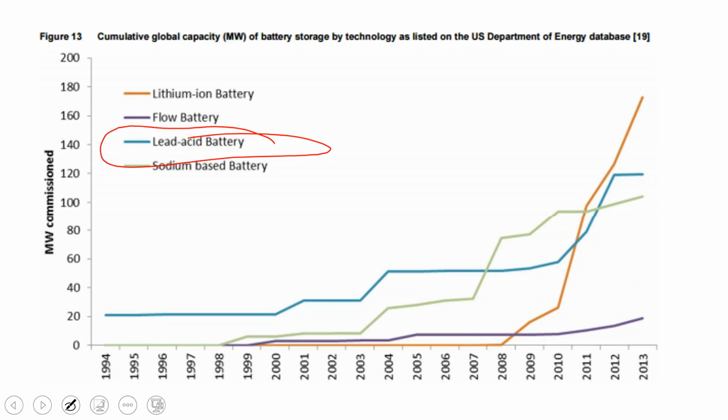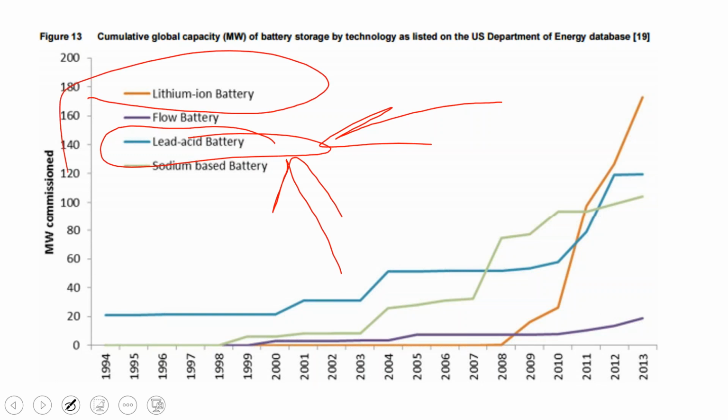It's the cheapest. If you are having a battery really just hang out and not do anything all day, like a residential backup battery, and you're not doing an expensive large array to really go off-grid without sacrificing quality of life, but if losing power at night during an emergency is acceptable to you and doing a small solar array is more affordable for you, there's really not much reason to go with lead acid at that point. The main advantage of lithium ion over lead acid, besides responsiveness, and it is more responsive, it is more efficient, but the main advantage is that lead acid batteries do require some maintenance, and we'll talk about that in a minute. Lithium ion batteries are more maintenance free.